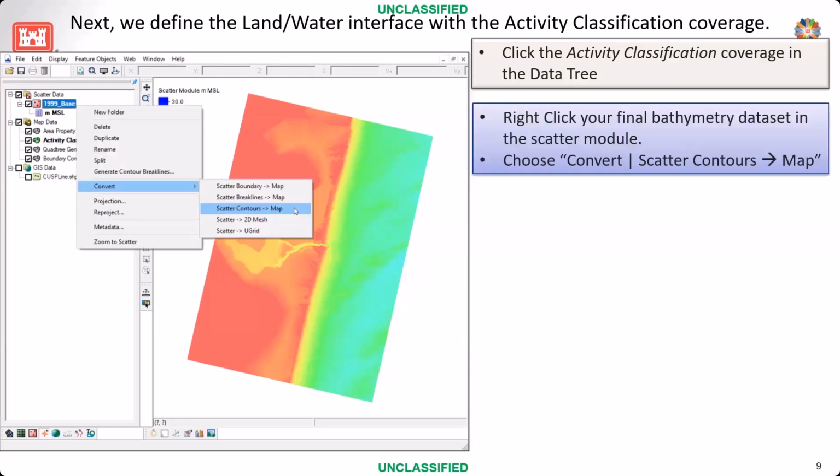To do that, we're going to leverage the information that we have in the scatter set. These are the steps that we take to do that. From the scatter data set, we can extract a contour that represents an elevation boundary that we care about. That elevation boundary is one way we can define active and inactive coverage, as opposed to guessing where we think the water may or may not go, if that makes sense.